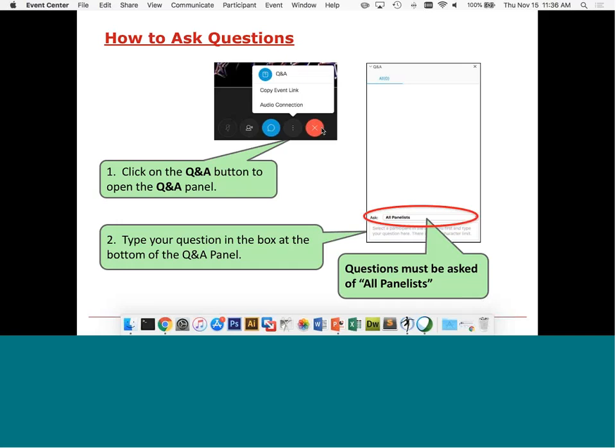Could I ask about Simulink? Another question from Naji Alabeji: are there any functionalities that allow for the use of OpenSim models in Matlab Simulink? I'm going to take that one, AJ. It's been a while since I used Matlab and Simulink, but yes, all the API calls you can wrap in M functions and then expose them as blocks in Simulink.